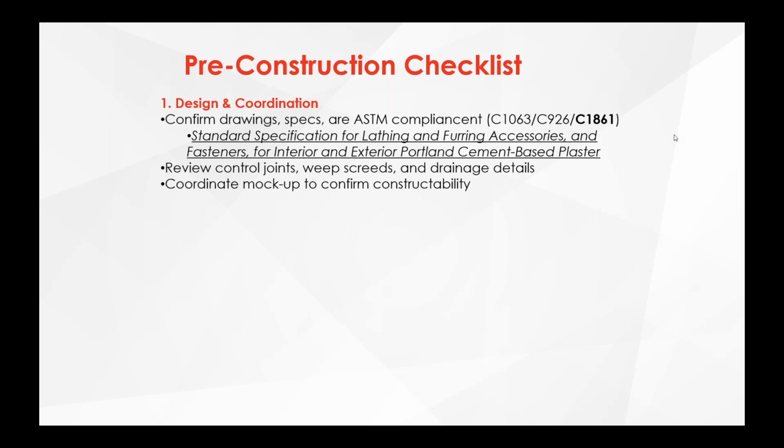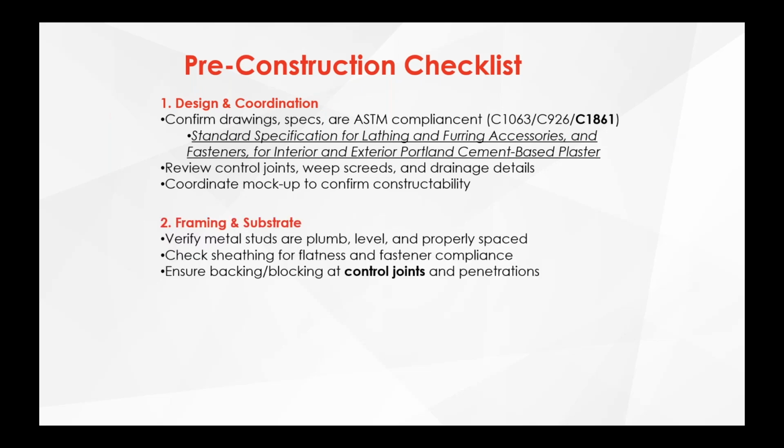Review the control joints, weep screeds, and drainage details. And I always highly recommend, if you can, do a mock-up to confirm constructability. I say confirm constructability because sometimes things look great on paper, and you go to build it and you realize some of the sequencing, some of the steps can't be done. So a mock-up to work that through is a good thing.